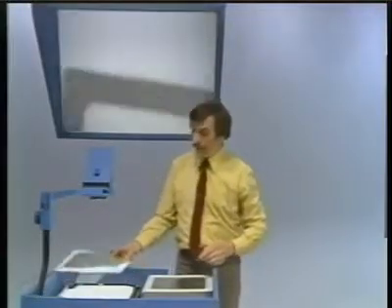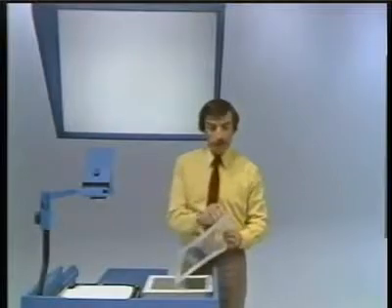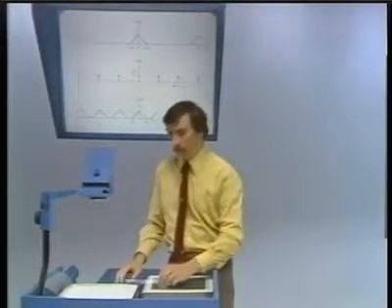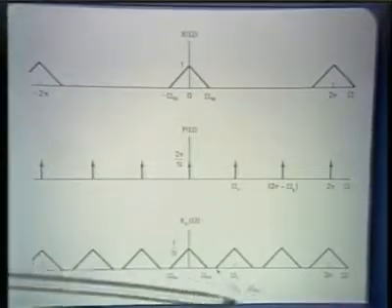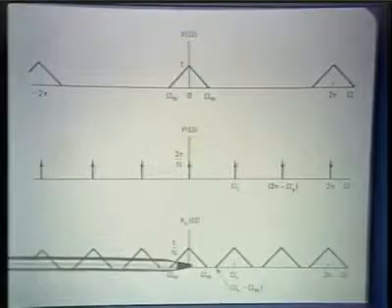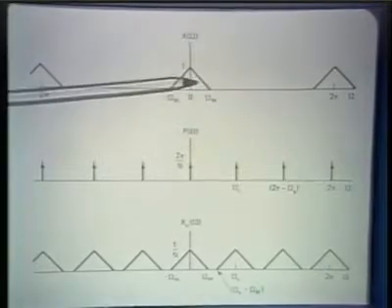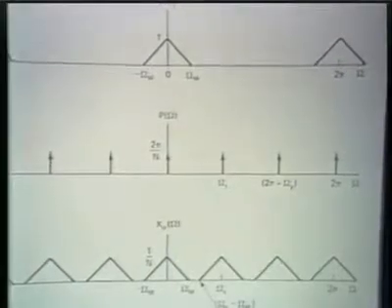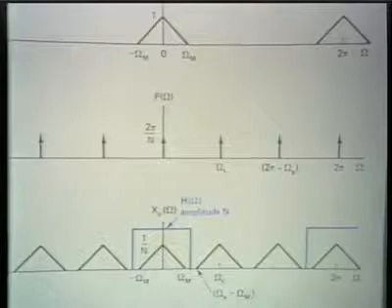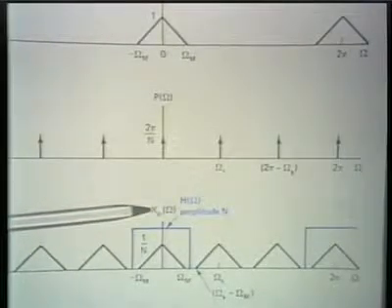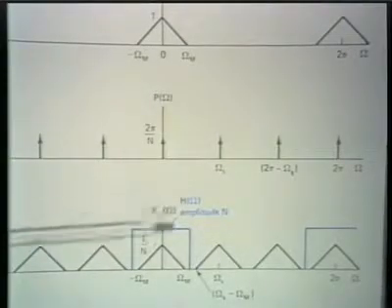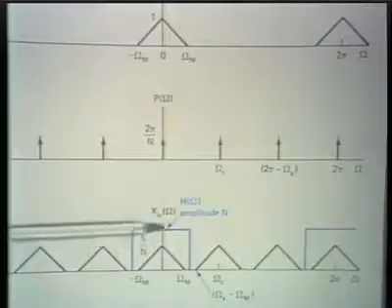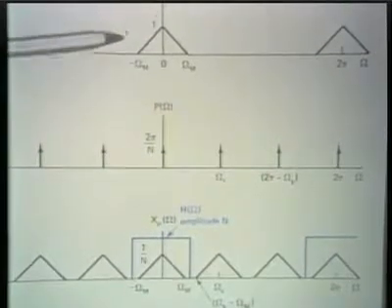Now, let's look more closely at the situation in which there is no aliasing. So in that case, what we have is a Fourier transform for the sampled signal, which is as I indicate here, and the Fourier transform for the original signal, as I indicate at the top. And the question now is, how do we recover this one from this one? Well, the way that we do that, just as we did in the continuous time case, is by low-pass filtering. In particular, processing in the time domain or in the frequency domain. This, with an ideal low-pass filter, has the effect of extracting that part of the spectrum that we identify with the original signal that we began with.